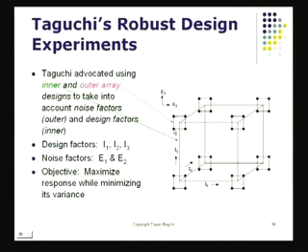The outer array brings in noise now, also in a controlled way. In this particular example, we've got 2 noise factors, E1 and E2. They are the environmental factors, and if they are at 2 levels each, I'm able to generate a little square. That's like a tiny matrix that will try to shake this prototype. The same matrix I'll be using here. So here I've got a product, a prototype, and I'm going to be shaking it with the environmental factors.